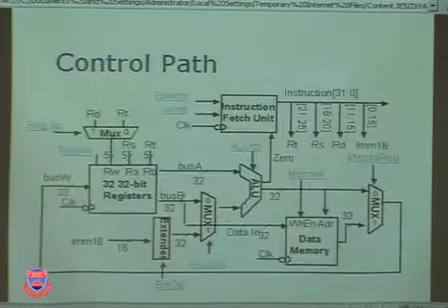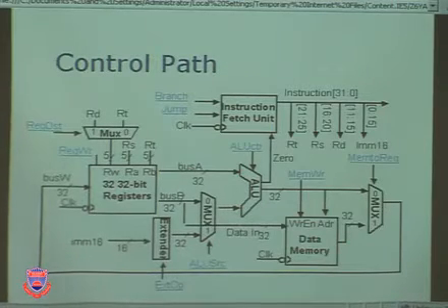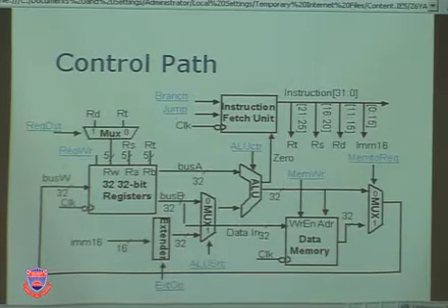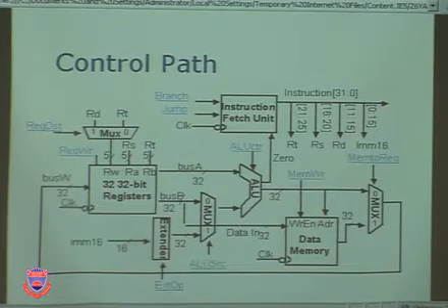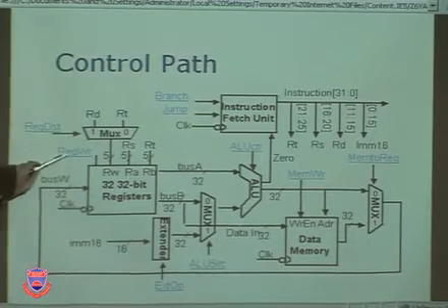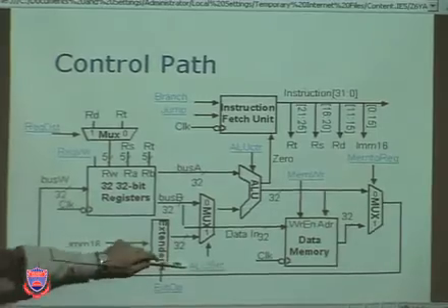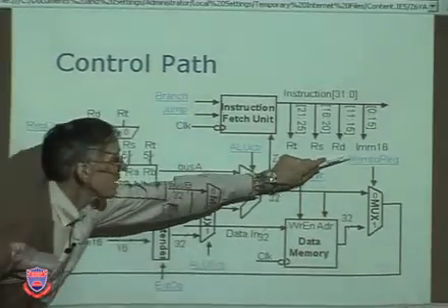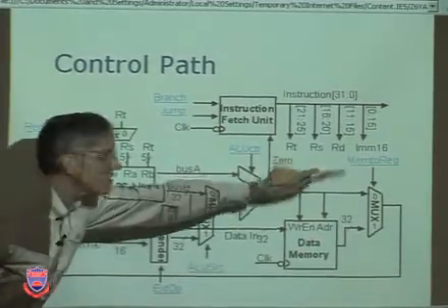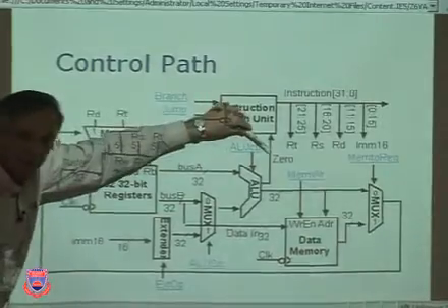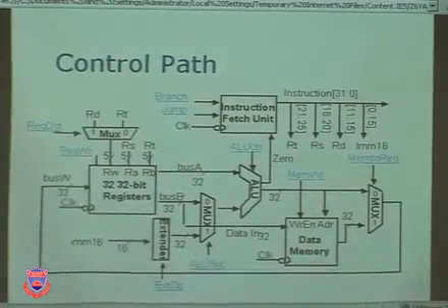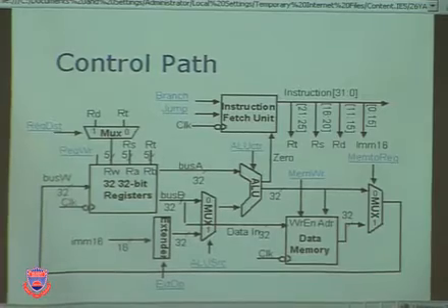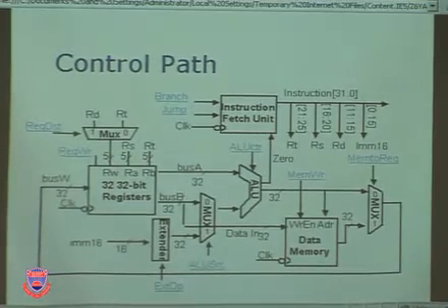So there's jumping. And so now here's the full picture of our control with the signals that we need to control. 1, 2, 3, 4, 5, 6 for the data path that are single bit, a multi-bit data path, that makes number 7 for the data path, and 2 more for the instruction fetch unit. 9 different control categories, all of which are single bit except this.